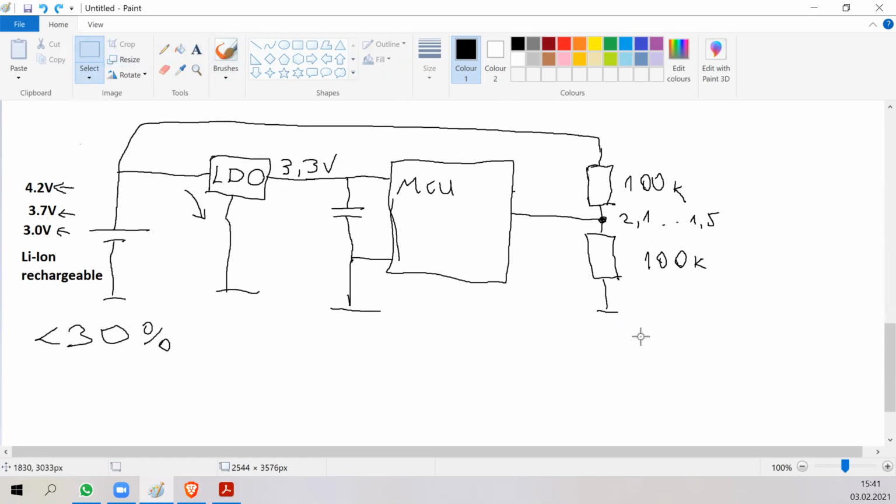So for those of you who don't believe that this is the best position, maybe you are lazy and you think, now I'll draw it the wrong way. Maybe many junior electronics engineers just connect the transistor in the bottom part because it's easier. This is an N-channel MOSFET, right? And N-channel MOSFETs are cheaper, they're widely available, and you can just set high to turn it on and set low to turn it off, right?